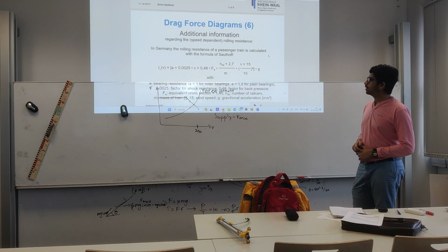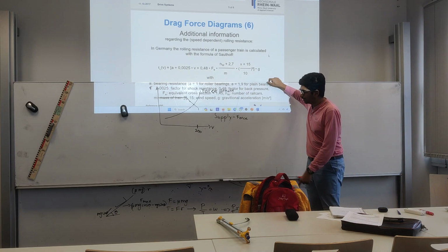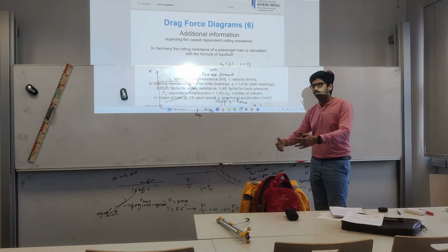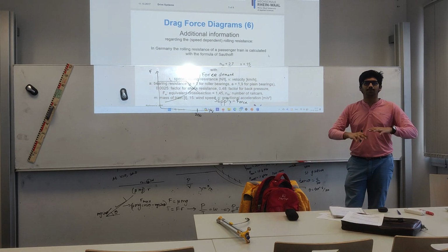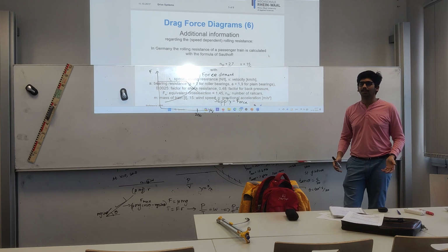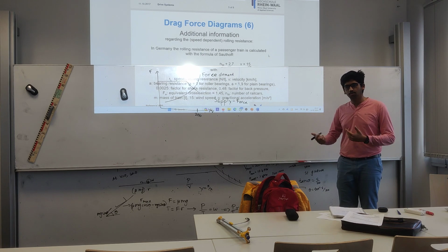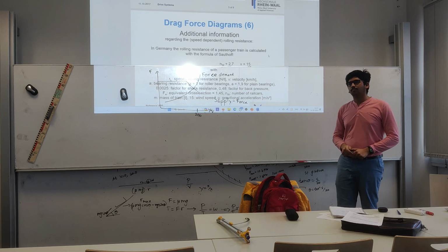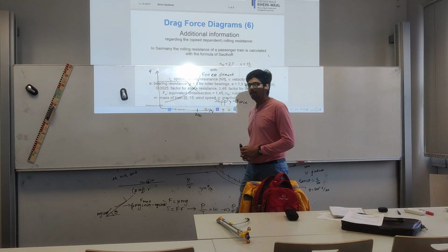But I was very surprised to learn what I mentioned earlier, that to increase the pulling capacity of a train, they increase the mass of the locomotive. Usually we think for efficiency we want lighter cars, lighter everything. But here, to be able to pull more stuff, you increase the mass of the locomotive itself. Yeah, it sounds counterintuitive.